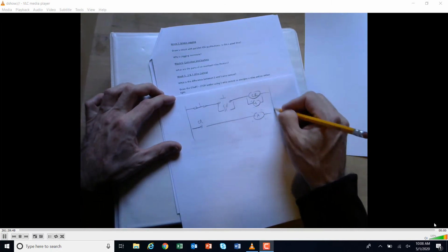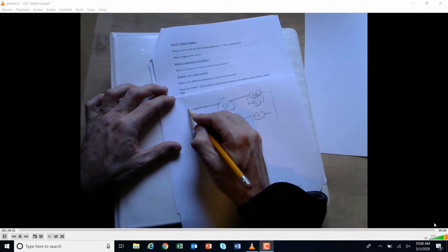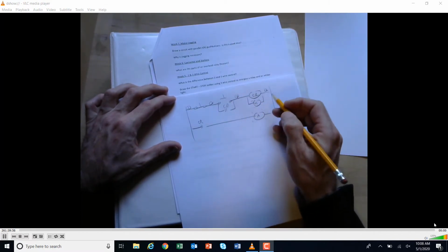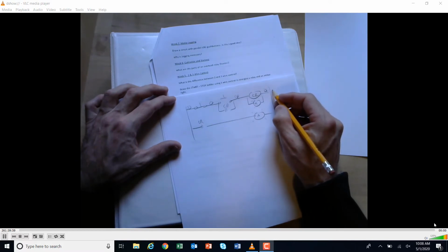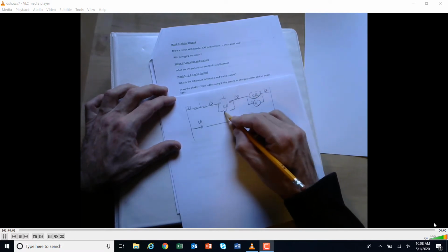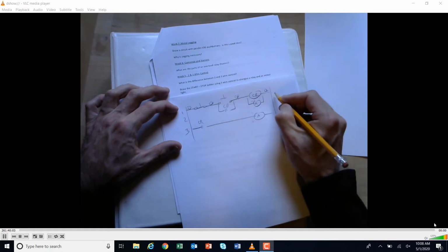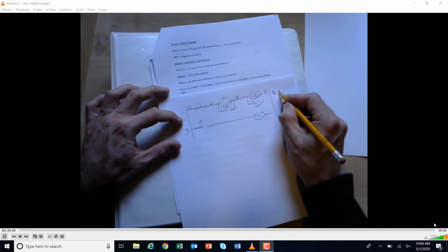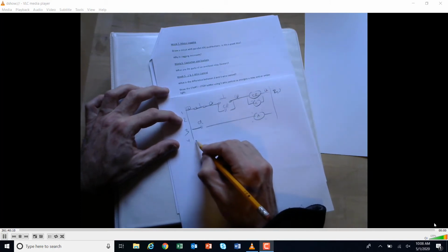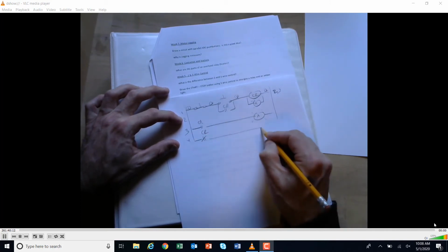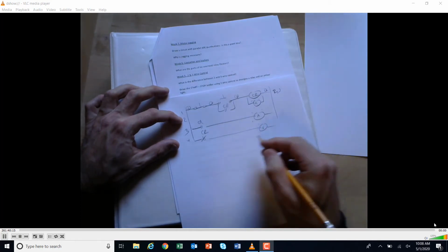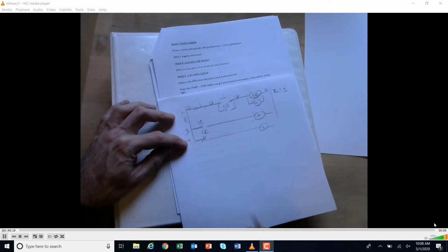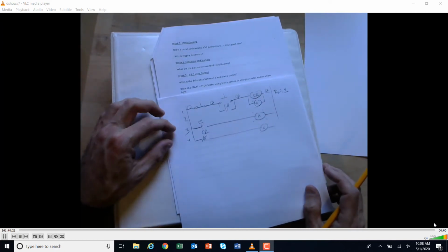And then we learned how to label your wires here, 1, 2, 3, 4, etc. And then we learned how to do the contact designation, that this control relay, in this case, would be used on 2. And it would also be used on 3 right there. And if I put a 4 here and I had a closed contact, let's say that did a green light for some reason, that would be 4 underline, meaning that it's closed. So we learned about how to do all that stuff.